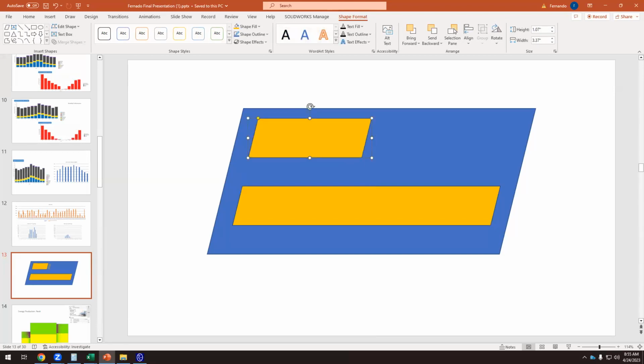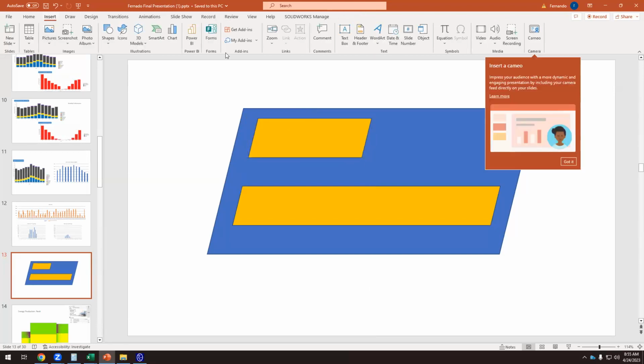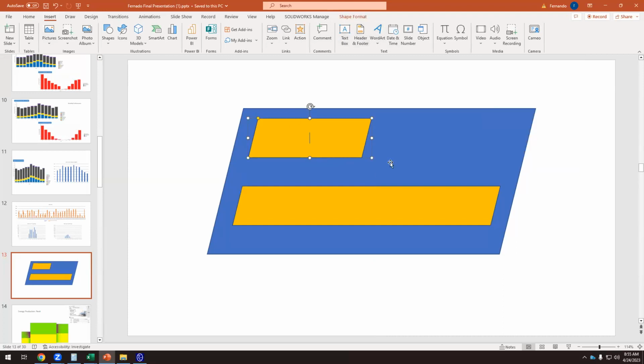Okay, so if we want this to be the zero energy building, we need like 220 square feet of solar collectors. And what was the area of PV panels? 550 square feet of PV panels. Okay, so now we have to figure out how we can place all that stuff.